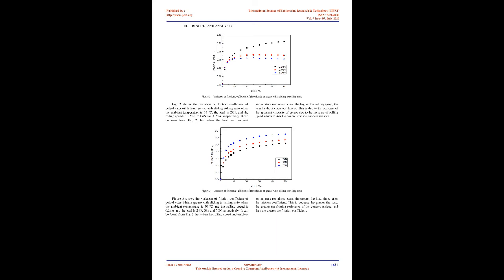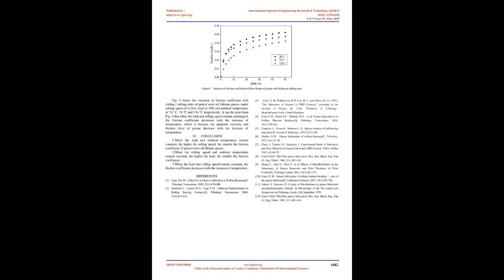Serial number, base oil, thickener, base oil viscosity, consistency 0.01 mm. Number 1: polyol ester oil, lithium 12-hydroxystearate thickener, 68 mm²/s, 280. In the test, the range of contact load is 24-70 N, the range of Hertzian contact pressure is 0.8-1.2 GPa, the rolling speed range is 0.2-3.2 m/s, and the temperature range is 30 to 130.